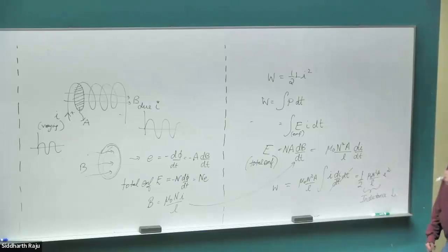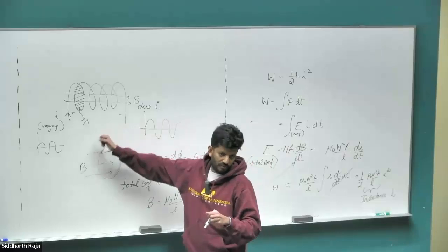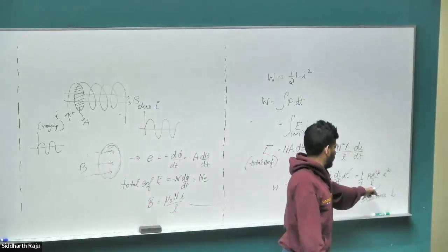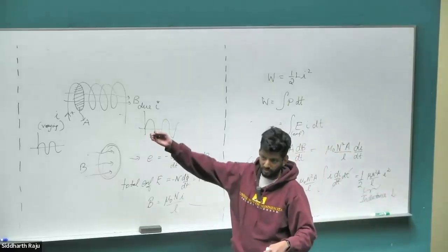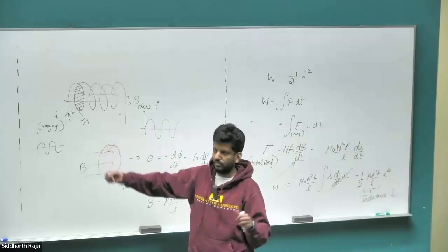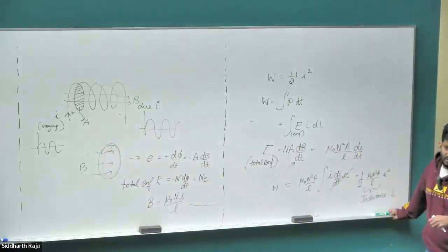Inductance L. So this L is a function of the material structure. So how we wind this coil will change what this inductance value comes out to be. So this is not a constant definition in terms of how we define flux. It doesn't matter how you wind your windings, flux is always the surface integral of the magnetic field. That is not the case with inductance. Inductance will change, similar to inertia. Inertia changes depending on the structure that you're looking at.